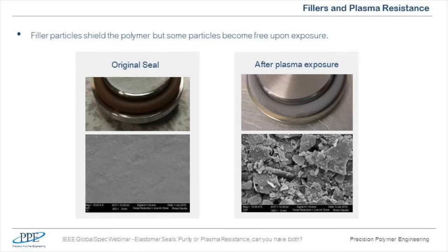So as I said, a bit of an extreme example, but we have seen that this material is very plasma resistant and tends to be amongst the best performing, with very low erosion rates. But you can see the obvious downside, which is the potential to release very large micron-size, or even tens, even maybe hundreds of micron-size particles into the chamber.